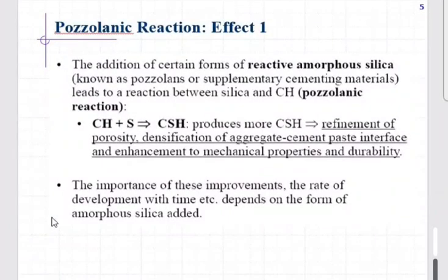Absolutely right. So if the pores are interconnected, that is called permeability. So it does not necessarily mean that if a system of cement or concrete has higher porosity, then its permeability will also be higher. That is not necessary. Because porosity does not mean permeability; it does not mean more pores. Permeability comes from whether these pores are interconnected or not. Clear?